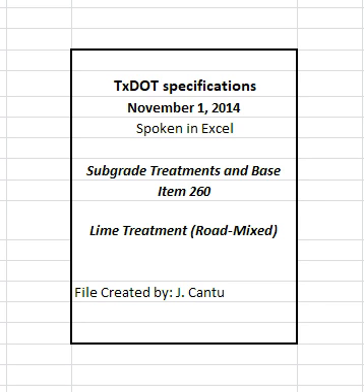4.7 Finishing. Immediately after completing compaction of the final course, clip, skin, or tight blade the surface of the lime-treated material with a maintainer or subgrade trimmer to a depth of approximately 1/4 inches. Remove loosened material and dispose of it at an approved location. Roll the clipped surface immediately with a pneumatic tire roller until a smooth surface is attained. Add small amounts of water as needed during rolling.